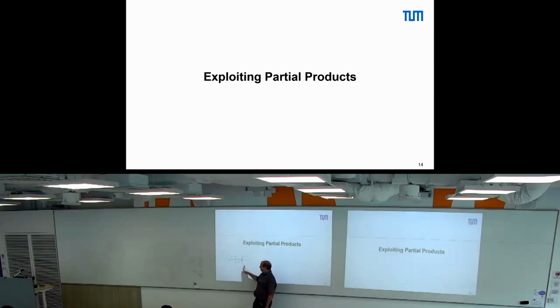So computation of these partial products is pretty simple. It's just AND gates. So with several AND gates, we can just do this, yes? So we just compute all these AND gates, and this one here is actually this here for the first step times this. This here is for the first step, also this one here.